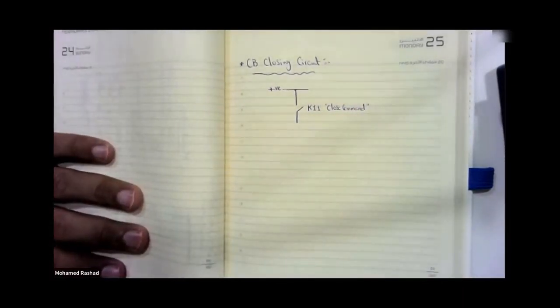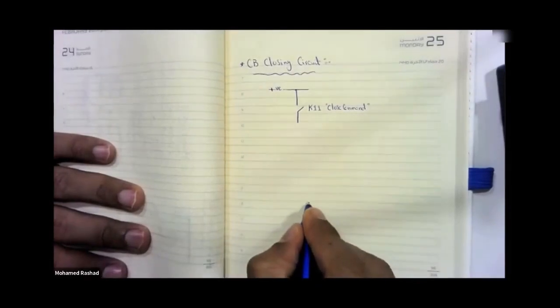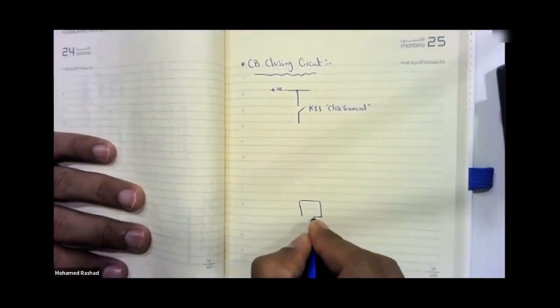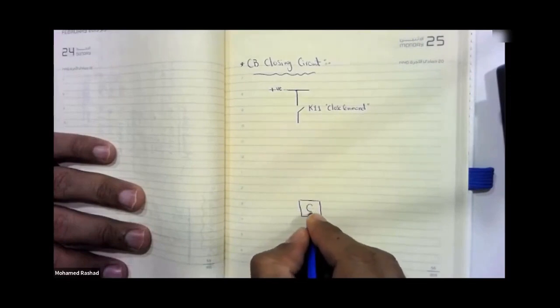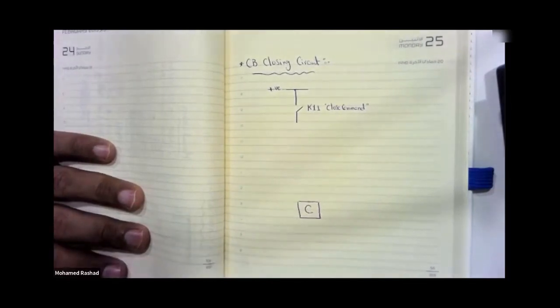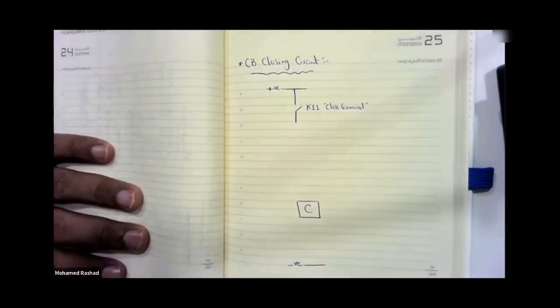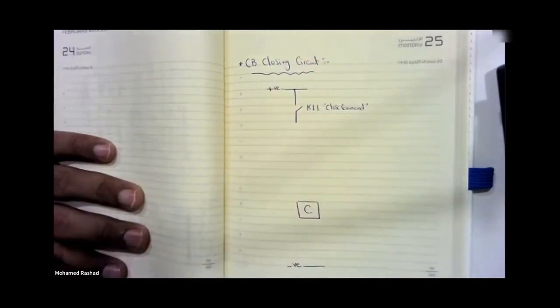Now, focus with me very well. It's saying that, as I go along with you, here at the end you have something called the auxiliary, or the solenoid, or the coil of the circuit breaker closing. So what is this? The closing coil, is that clear? And what is supposed to be connected to the closing coil in the end? It should be connected to a neutral. Now, elevate your imagination a bit with me and consider this as all the connections leading to one point.